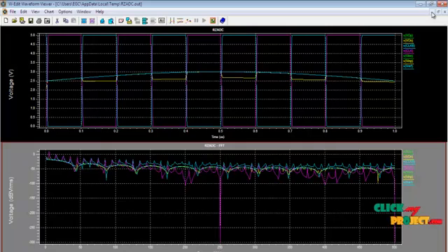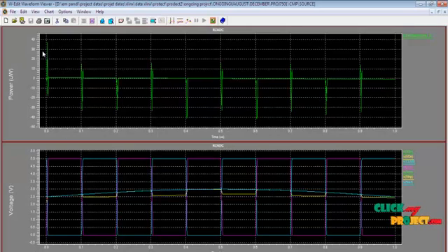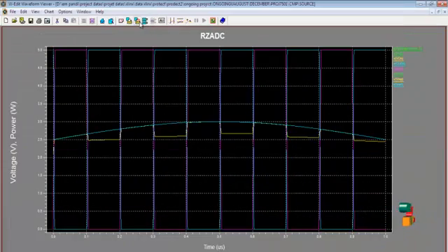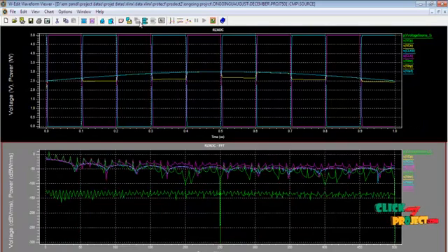And next we see the power output for the corresponding input and output data. So this is the power output. The power range is around 30 microwatts. So this is the range, and this is the unit of the corresponding output power. So these data will be shown in the waveform format. If you want the FFT analysis for this, click the FFT, then the output will be displayed. This is the power value, and these are the input and output data values.